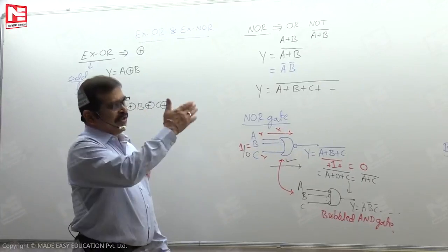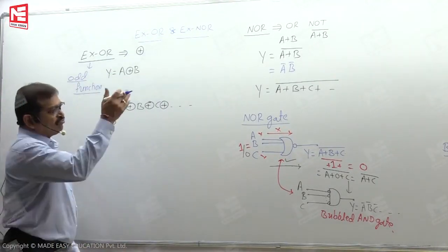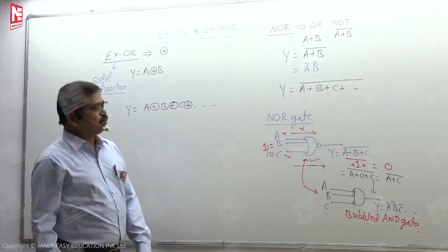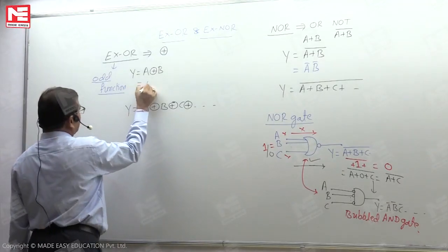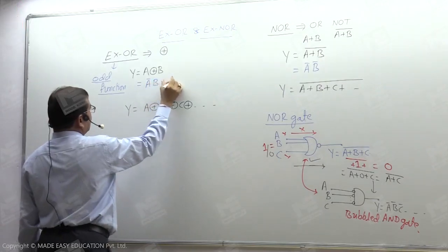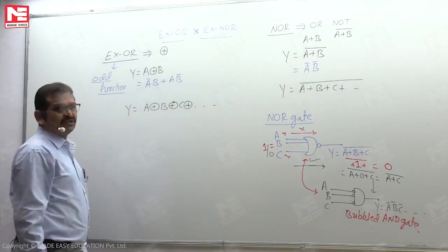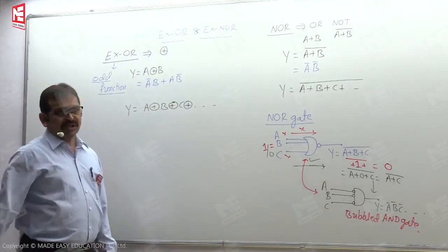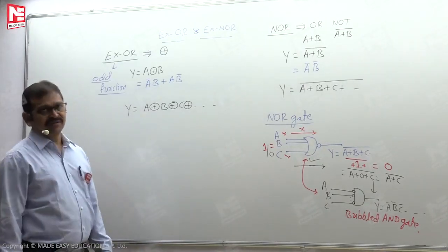From the 2 variable truth table, if we try for the SOP form, we give it while looking at the middle 2 rows of the truth table. One product is A complement B, the other product is A B complement. Among these 2 products we have an OR operation, so the SOP expression for this 2 variable case is A complement B OR A B complement.